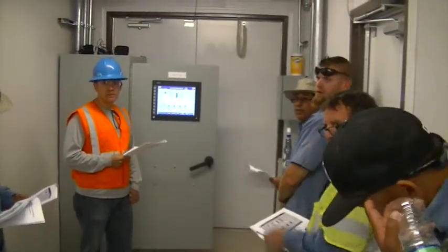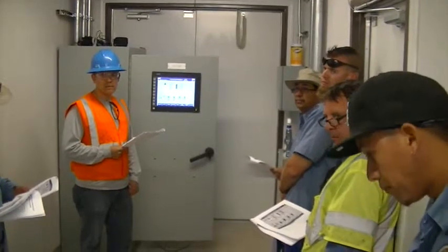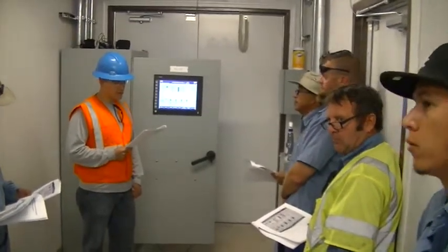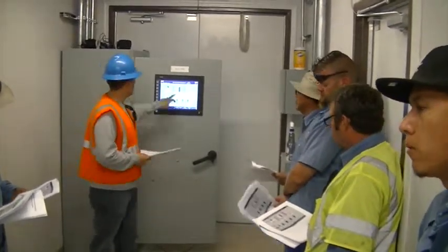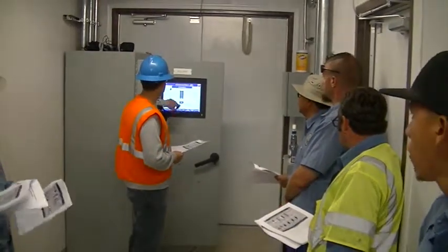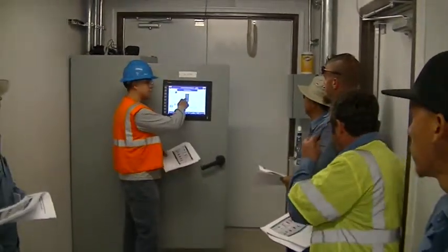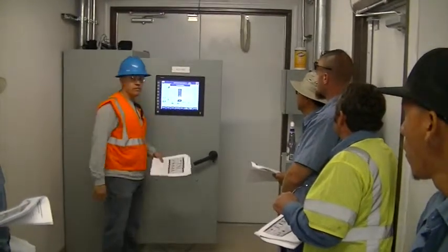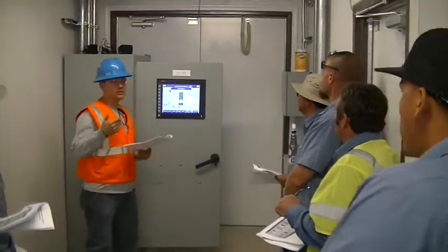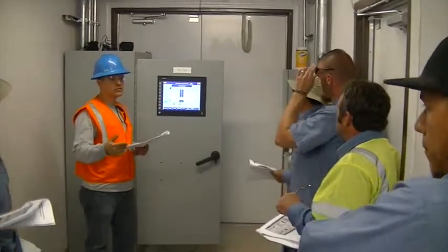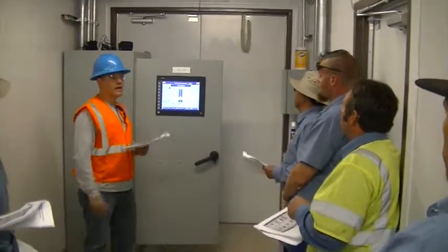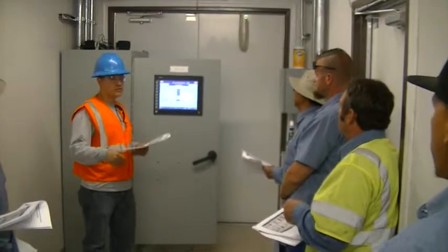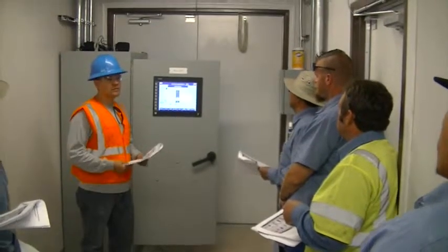Does the PIT on the tank also function in the same way? Yes, it has the low alarm. So you set this up, click on there, see this low limit? That will lock it out as well. So if the float fails, it'll still go off the pressure, the level transducer, and it'll lock it out as well. So there's a physical lockout, and then there's a lockout in the PLC.